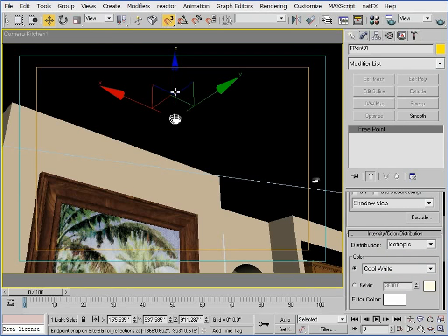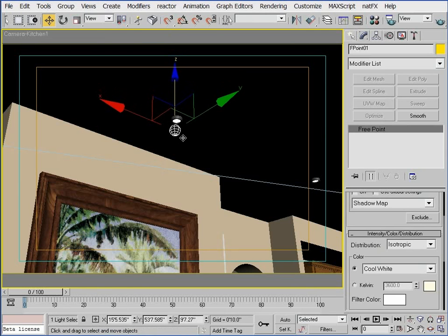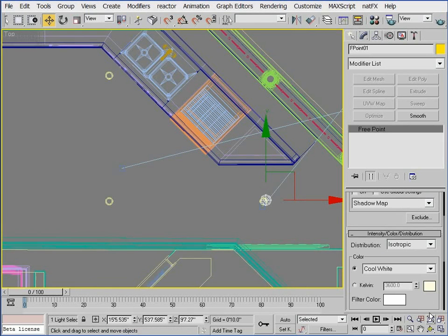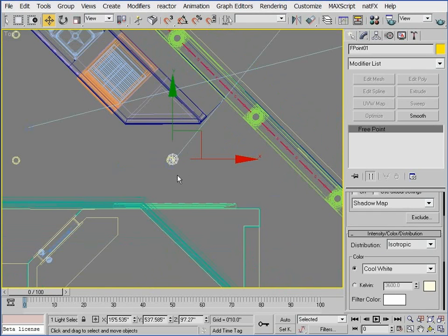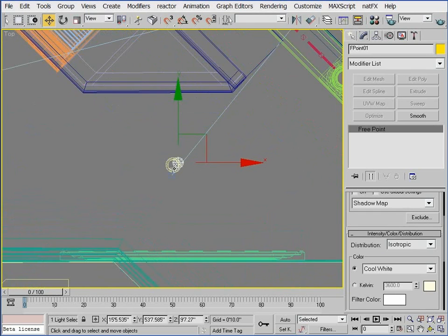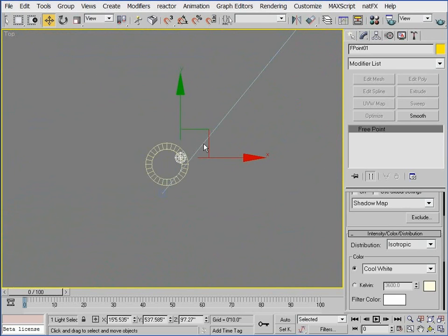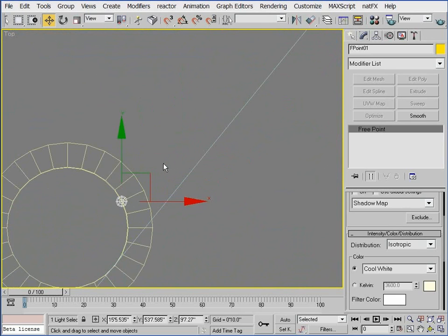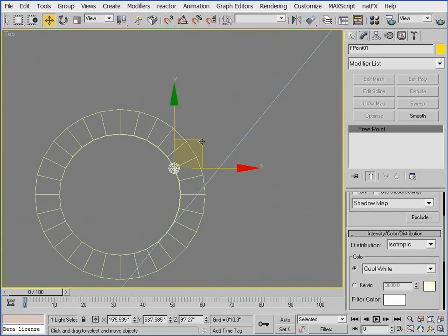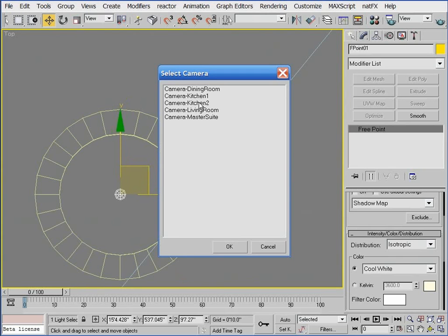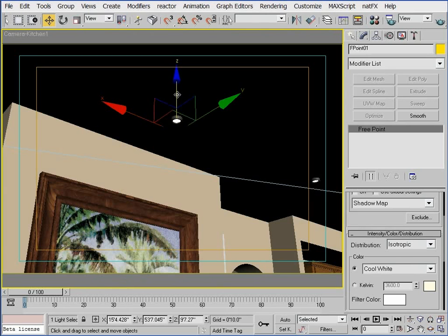I know that if I place the point light too close to any surface, I'll see a hot spot develop, and this wouldn't look good on my ceiling, so there shouldn't be any hot spot of any kind, and I want to prevent this. The light bulb in these fixtures really don't have a direct line of sight to any part of my ceiling, so I can't allow any amount of hot spot to develop because it would look unrealistic. So I need to place the light several feet below the fixtures and hope that I don't see a hot